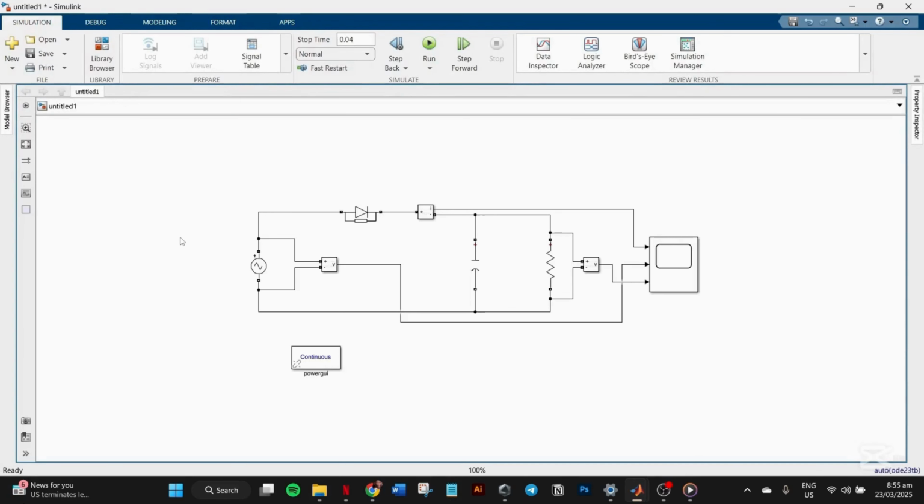The half-wave uncontrolled rectifier with C filter is commonly used in battery chargers, converting AC to DC for charging batteries, signal demodulation, extracting useful signals from modulated carriers, DC power supplies providing low-cost DC power for small electronic devices, and voltage measurement systems used in analog voltmeters for converting AC to DC for easier measurement. We can see how the simulation effectively demonstrates how the half-wave uncontrolled rectifier with C filter works. By using a simple capacitor filter, we can significantly improve the quality of the rectified signal.